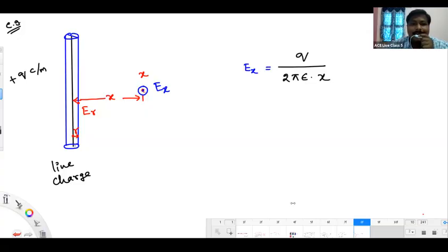Krishna Priya, resistivity is a constant number. It won't change, even though you change the dimensions. Resistivity is defined for the material. Resistance is defined for an object. For example, if I have one material, this material will have some resistivity, and this conductor, or this body, will have some resistance. That resistance depends upon the resistivity of this material and the dimensions of this body. Okay.